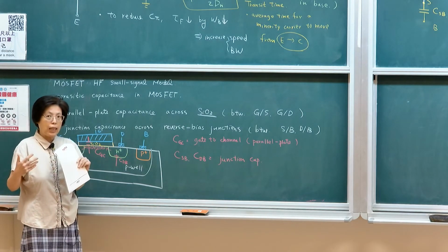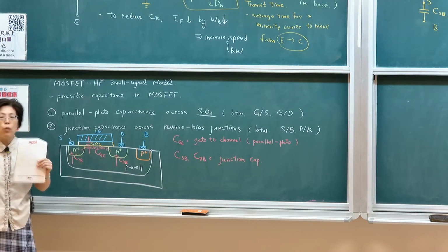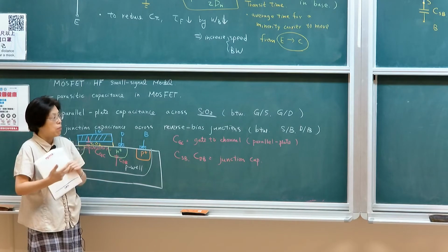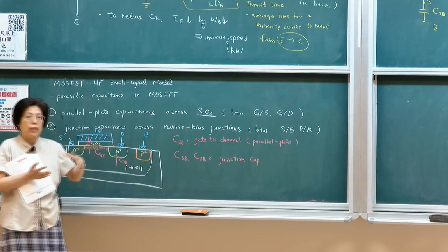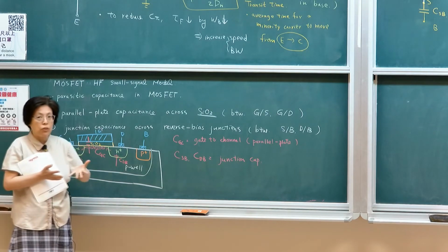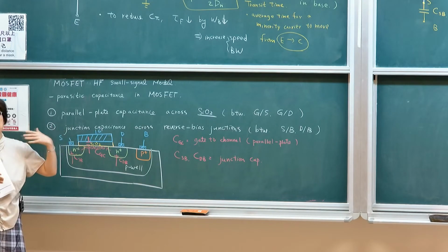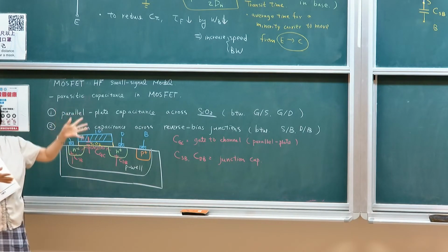So it's like intrinsic gain. Intrinsic gain is when I have the most ideal case, what is when the gain is limited by its channel length modulation effect. So that will then lead to its ultimate gain of the circuit, the ultimate ceiling of a particular technology. This is also the same.